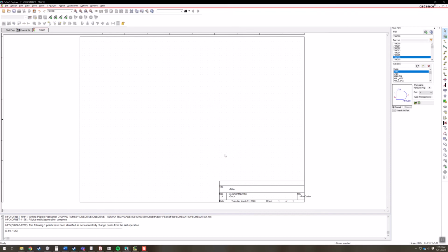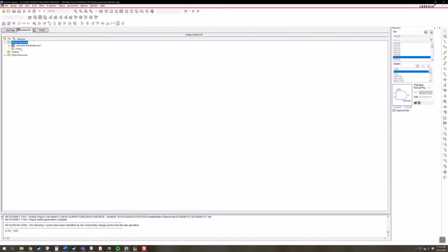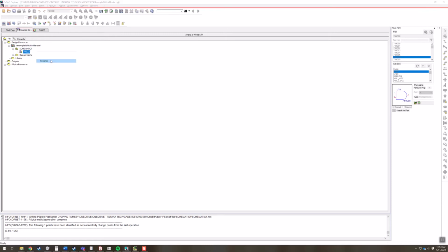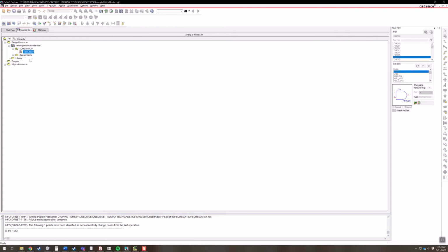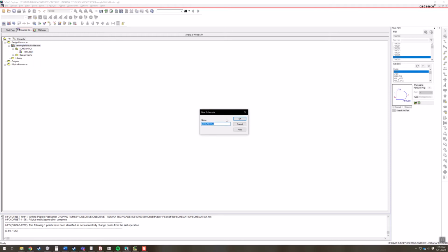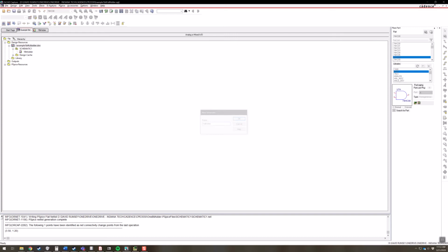So I'm going to show you a way, going back to just our normal size, is creating something called hierarchical blocks to do our simulations. So first off, I'm going to expand this area and scan the schematic, and I'm going to rename this, and I'm going to call this a 1-bit adder. And what I'm going to do now is I'm actually going to create a new schematic, and I'm going to call this schematic a half adder.